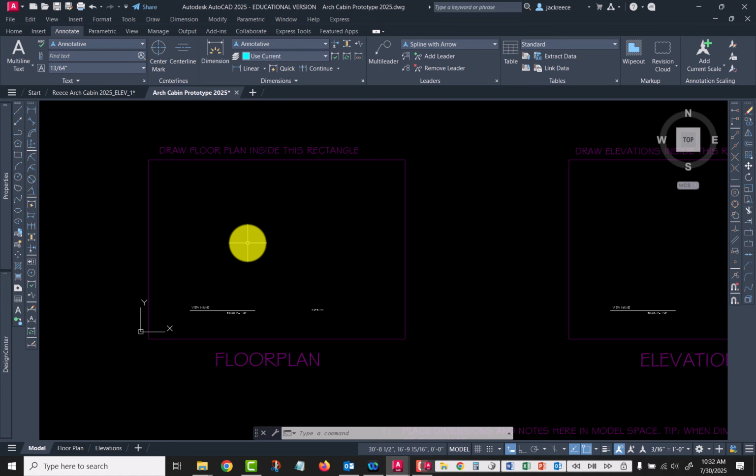And that's kind of the old way of setting up text styles and dimension styles before they came up with the annotative styles. And you'll see some people still use that. I find it easier just to go with the annotative style, so you set all of your settings to what you want them to be in paper space, and then you set the annotative scale. One-time deal.